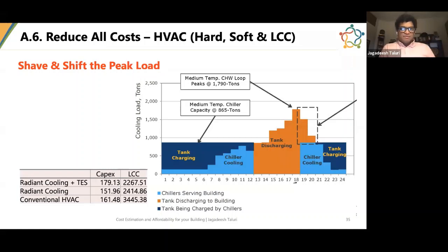the cooling requirements. But instead of doing that, what the system we have designed for this building does is, we will not be using the chiller plant between 12 o'clock in the afternoon and 6:30 in the evening, where my load is higher. The chiller plant is essentially going to be shut down. We are going to be running the chillers after 6:30 in the evening till 12 o'clock in the morning, when the climate is benign, when the tariff is lower, when conditions are optimal, and there's no occupancy. So in that time, we'll be running the chiller plant.